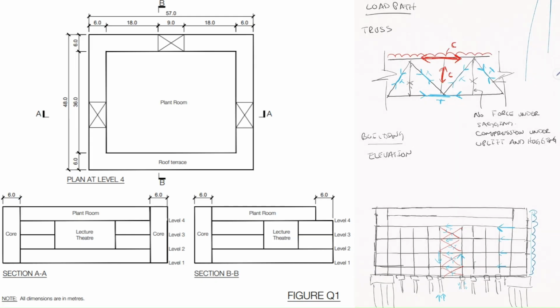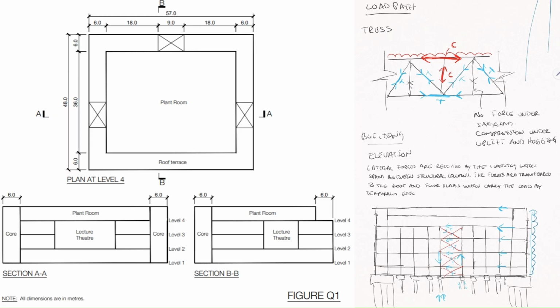For the steel structure, scheme 2, there are not going to be shear walls, and instead there are just going to be some cores where the stairs and the lift are that are going to have vertical bracing. And then it's ideal to show how the lateral loads are going to be transferred through the cross bracing.